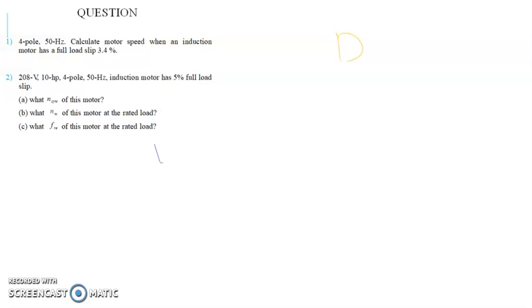Okay, another concept is regarding the poles. For your motor to work, you have to have a magnetic field generated inside your stator in terms of pole settings. The minimum number of poles is 2. One set of poles means North Pole and South Pole, and then it comes with another, in even numbers: 2, 4, 6, 8, like that. So let's say we have 4 poles.